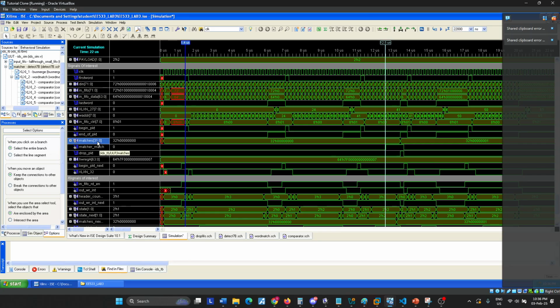The matches signal here essentially determines how many malicious patterns have been matched with the input data. So out of 100 packets, if it only finds the malicious packet once, it will say 1. If it finds it twice, it says 2. A counter for malicious patterns being matched to the input. In the waveform, we see that only one packet has been found from a number of packets that were sent from the test bench. So that's why the count here is 1.